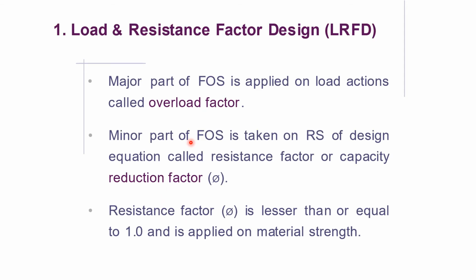First of all, LRFD. In the LRFD, the major part of the factor of safety is applied on the load actions, called the overload factor. The minor part of the factor of safety is applied on the right side of the design equation, called the resistance factor or the capacity reduction factor. In the start you have seen the basic design equation. On the left side there are loads and on the right side there is the material.